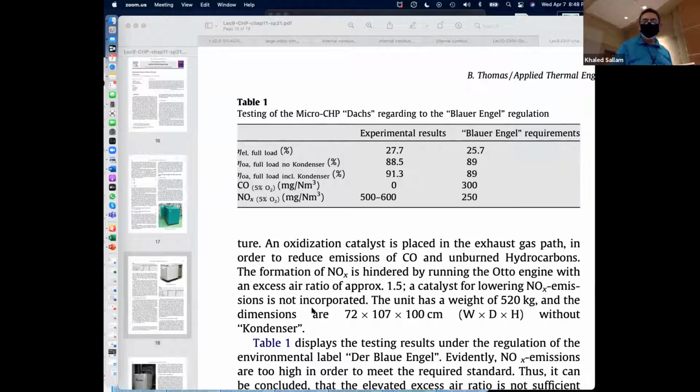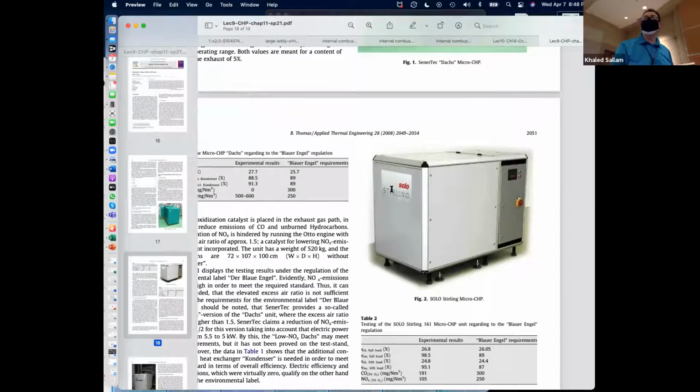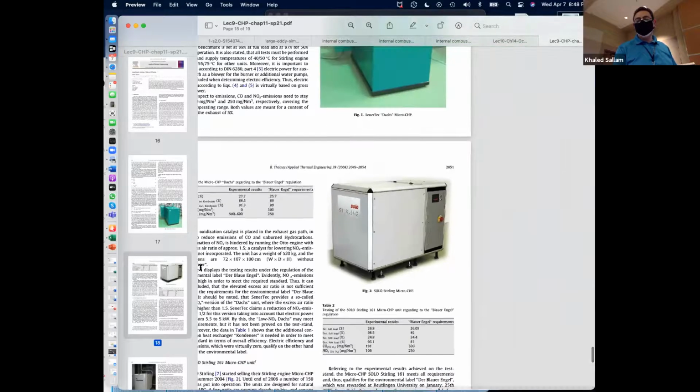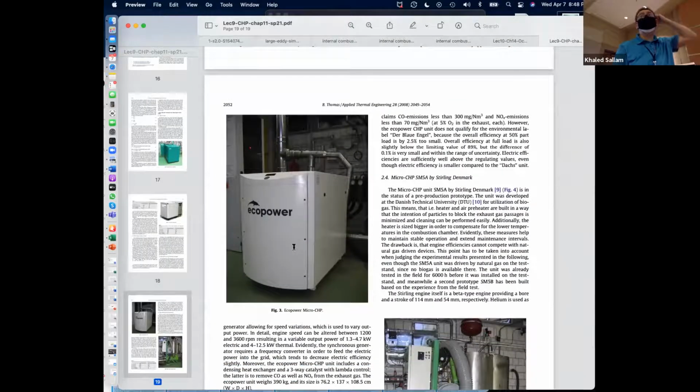Huh? That can happen. Of course, emission is also a problem because a small unit like this will not have the control on the combustion process like a big power plant. So there are difficulties with emission, with efficiency, and with the cost, the price per kilowatt hour on those units. There's something called economies of scale. If I'm making 1,000,000 units, or if I make something really big, it's going to be cheaper than something very small. And if you have spent time reading about the big GE gas turbines, they will tell you why they are making them bigger and bigger, because of the economies of scale.